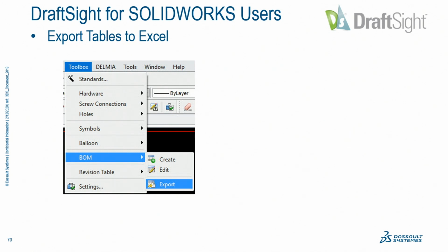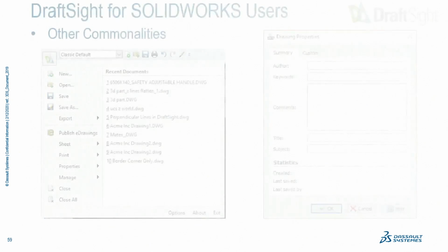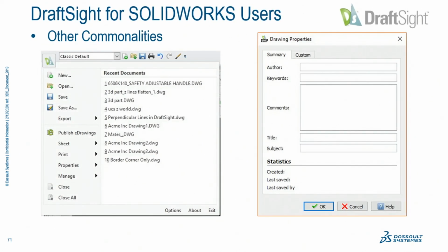Oh, you're talking about the sheet manager, the one that's in AutoCAD? Yeah. Oh yeah, right there. So you go right to sheet, and that's where you can get to that manager. And when you click on that little icon, that's where this pops out, okay?